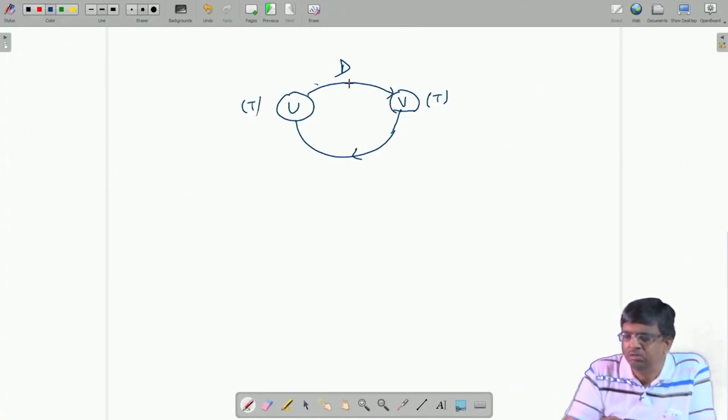They are pipelined. So, if I had only the upper path, upper edge or upper path, critical path would have been just t, but there is a lower path, lower edge. Here there is no delay. So, first you have to carry out a job at v taking t amount of time, in the same cycle give it to u, it has to spend another t amount of time in the same cycle. So, the two times got added, 2t. So, from upper half critical path is t, from lower half critical path is 2t, you have to take the larger one, largest one. So, critical path here is 2t. So, to avoid that I want a delay here. Okay, to avoid that I want a delay here. How to have a delay here?